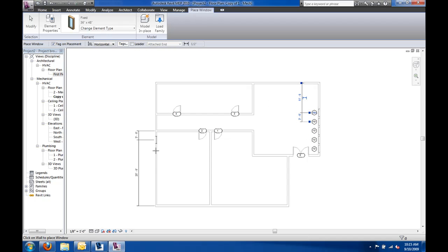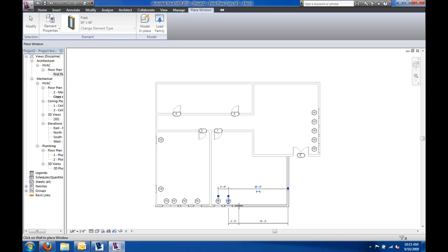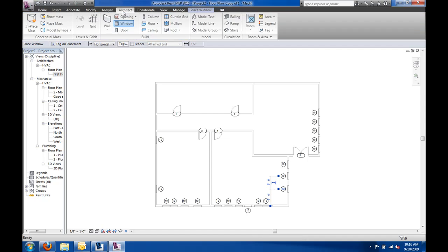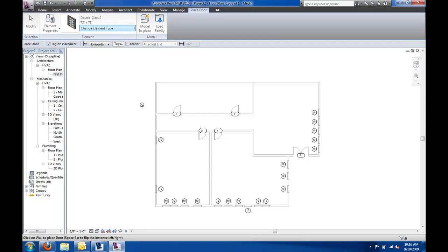We don't have any windows in the bathroom, thank goodness. We got a couple here. We got a lot along this wall. And again, placement's not important. Just get the right amount of glazing. I should say placing is not important within a wall, but you need to make sure that if it's a west-facing window, obviously that's going to have a bigger impact in certain areas of the country than a north-facing or south-facing. So make sure you got it in the right orientation.